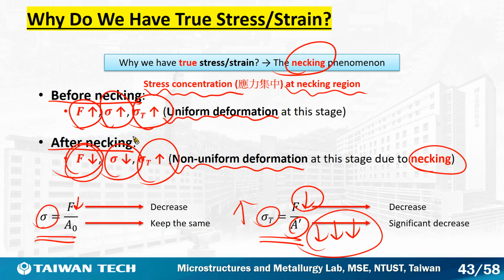Otherwise, if you just use engineering stress and engineering strain, you will figure out that after necking, the stress will decrease, so the material strength will decrease. And actually, this is not true. During the process, strain hardening will occur and the material strength will increase all the time.